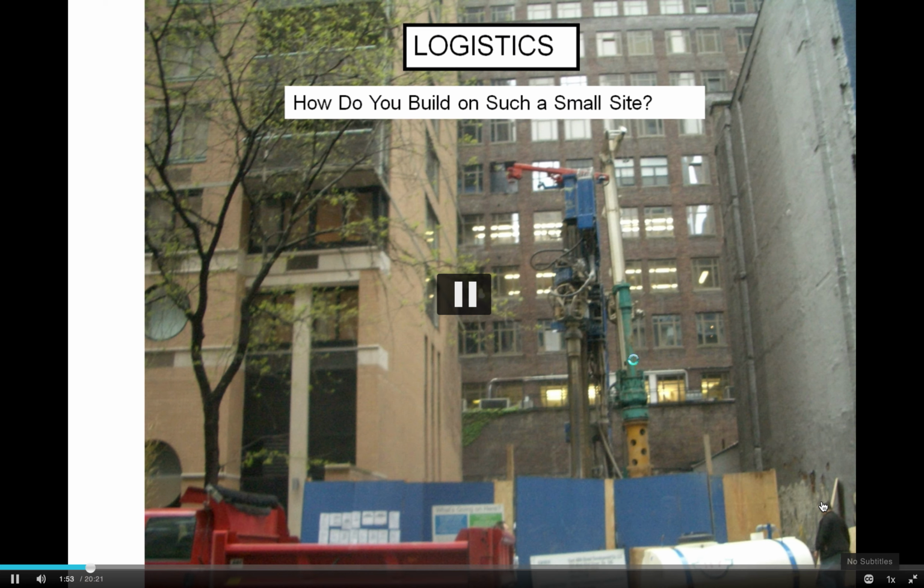that you have. And we covered some of that in the geotechnical discussion, how do you slope excavations of a basement when you don't have room to slope, and you have to do a lot of stuff, including underpinning, dewatering, driving sheet piles, a bunch of different methods and techniques to be able to excavate that foundation, yet protect the workers and protect the adjacent surroundings. So the same thing happens as you go further up